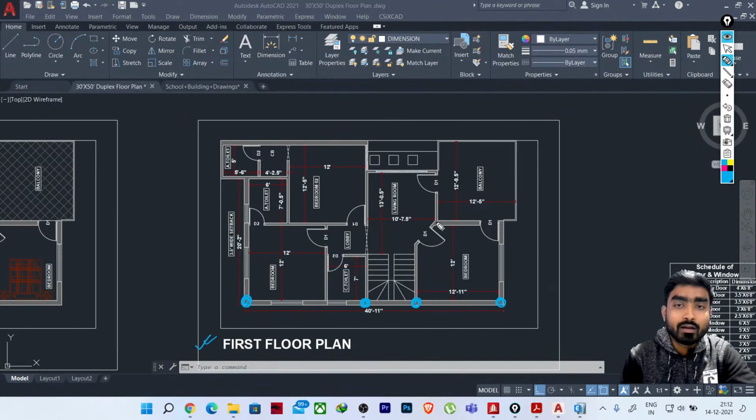Okay. And you will see that even if we place a column here, it will not disturb the ground floor plan, or anything in terms of architectural placement, maybe the door placement and all, in the ground floor plan also. So we can put one column here. Obviously, it is not recommended sometimes. It is always recommended to put 4 columns at the 4 corners of the staircase. But in that case, we can go with this here because it is just G+1.